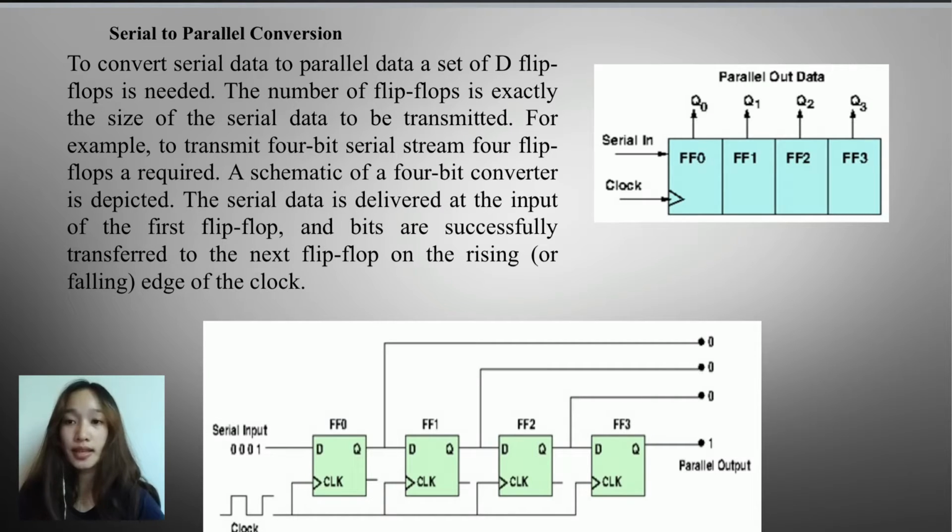The first one is disable the output bus, so the converter cannot send output data. Second, load all the bits into the outputs of the flip-flops by moving them one bit at a time using the clock. Lastly, once all the bits are loaded, all the flip-flops have 1 bit stored in the Q pin, then enable the bus operation. The 4 bits are sent at once.